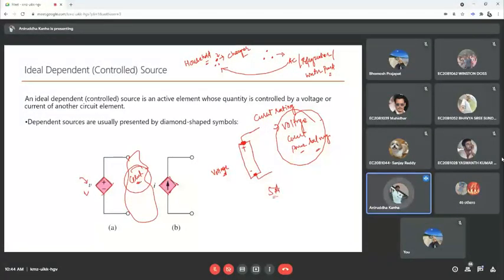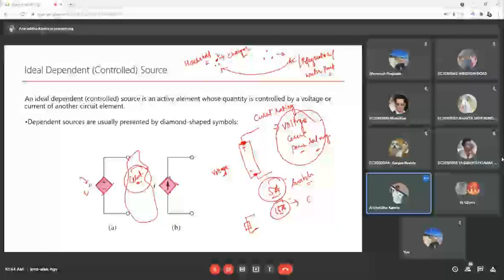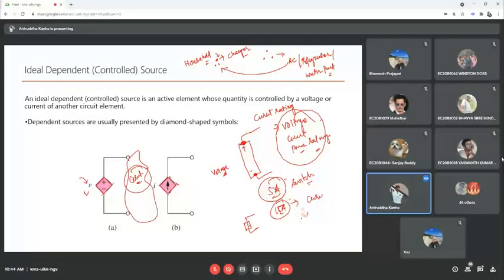One is called the 5 ampere switch, and the other one is 15 amps. Why 15 amps? Even though the voltage is the same, the load is high, and it has to withstand the high current. Because of that, the power dissipation will be high.